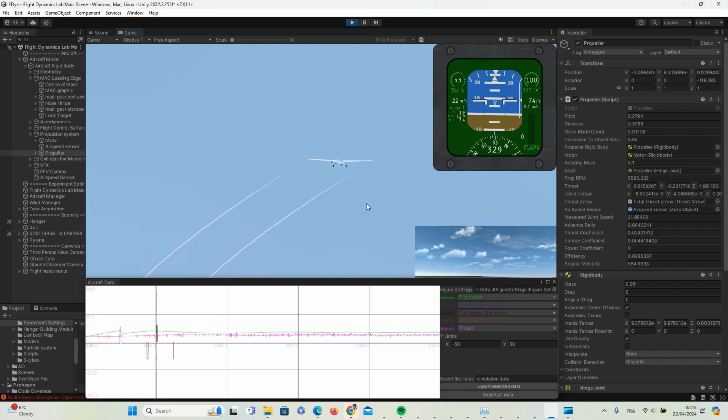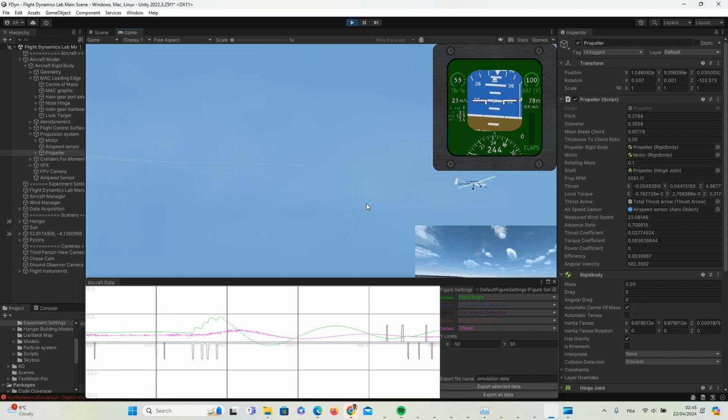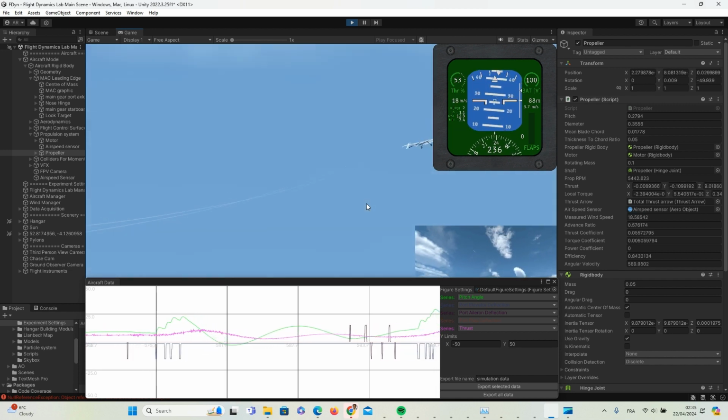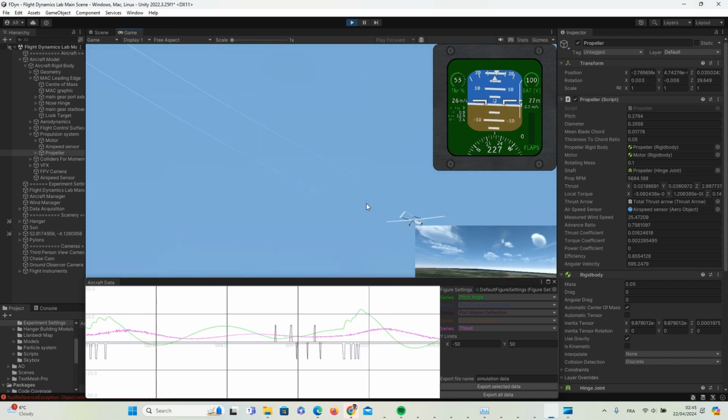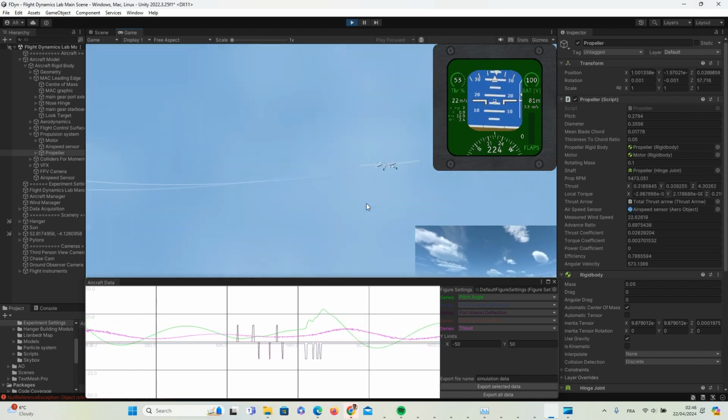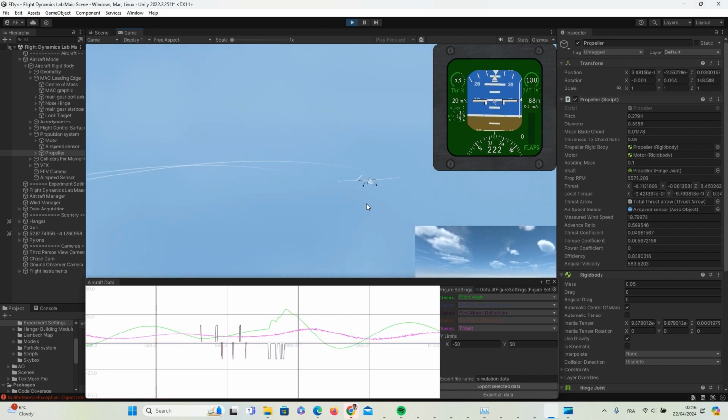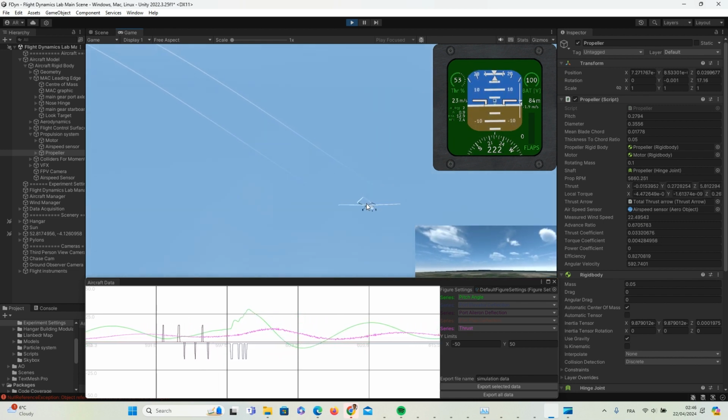A throttle of about 55% allows the aircraft to fly trimmed in cruise, as is demonstrated here. The aircraft's phugoid frequency is about 0.1 Hz, and as is shown in this demonstration, the aircraft naturally restores itself in this phugoidal state without requiring corrections from the pilot.